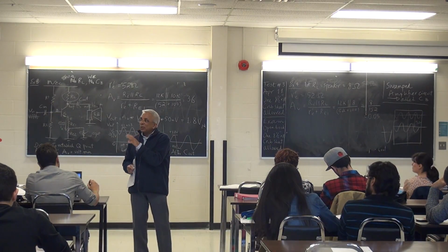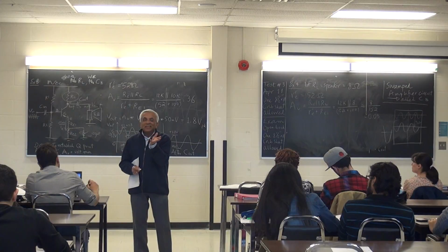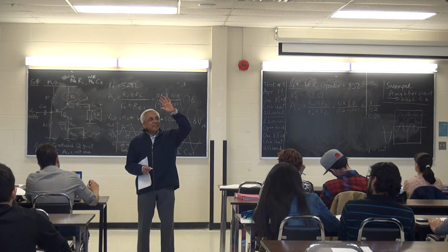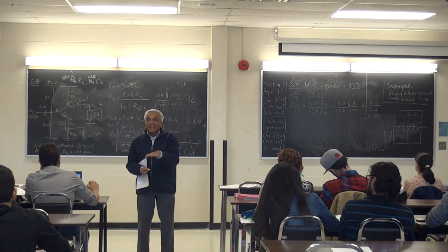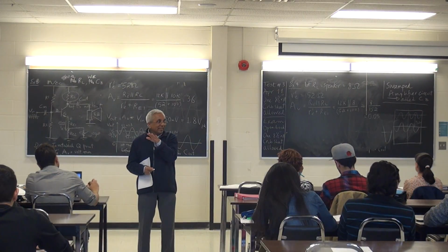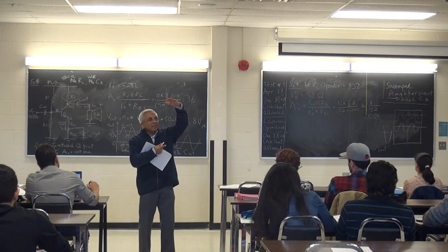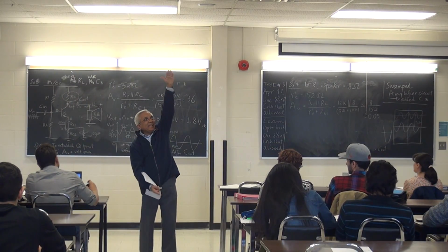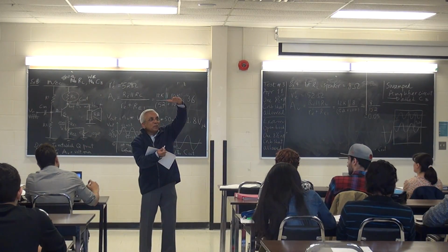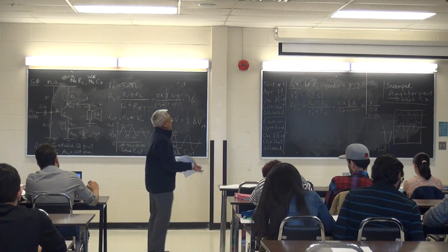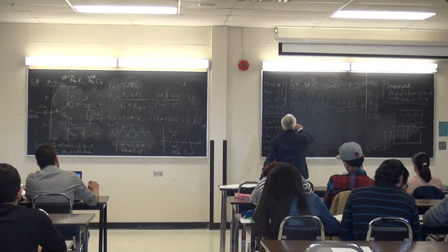But what if that load was 8 ohms? My gain is a negative gain. It's even less than 1, isn't it? And any gain less than 1 is my signal, instead of getting bigger, is now doing what? Shrinking. So that's called attenuation.